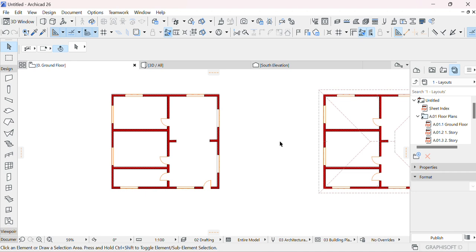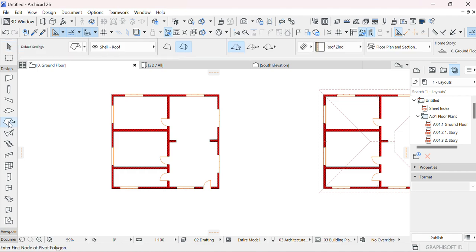So let's move on to the next stage of drawing a hipped roof. We go to our command, roof. By clicking that, I'm telling the ArchiCAD program to draw a roof. So I click this. Still, I continue to use the option that I used for my hipped roof. Since this is rectangular, I will use that option to speed up my work.